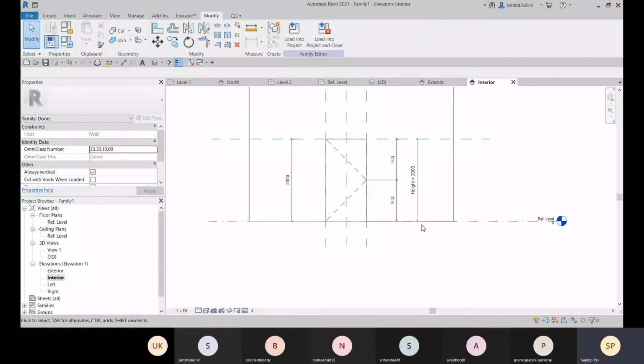But if I'm applying this from any particular 2D view, I cannot create a 3D view, or I cannot assign all the edges of that 3D object. So what I do is connect with the reference plane where the object is created, so that if I change the reference plane, the object will be reflected.